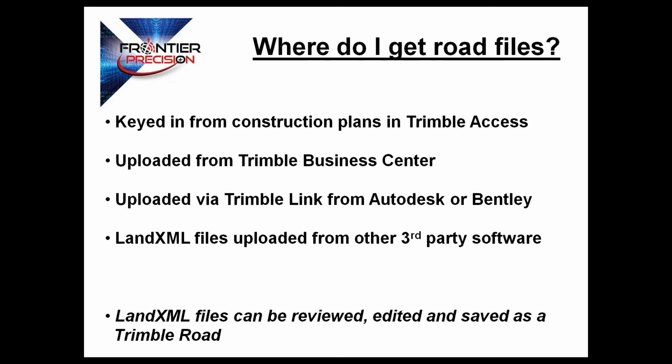The next question would be, okay, that's great, but where do I get these road files? So just some different ways. There's obviously going to be more than this, but these are the common ones. First way is keying the road in from a set of construction plans in Trimble Access. Maybe keying a road file into TBC and then uploading it to the controller. Also uploading it via Trimble link from maybe an Autodesk or even a Bentley product. And then lastly, a land XML file that was maybe uploaded or copied to the controller from a third-party software.